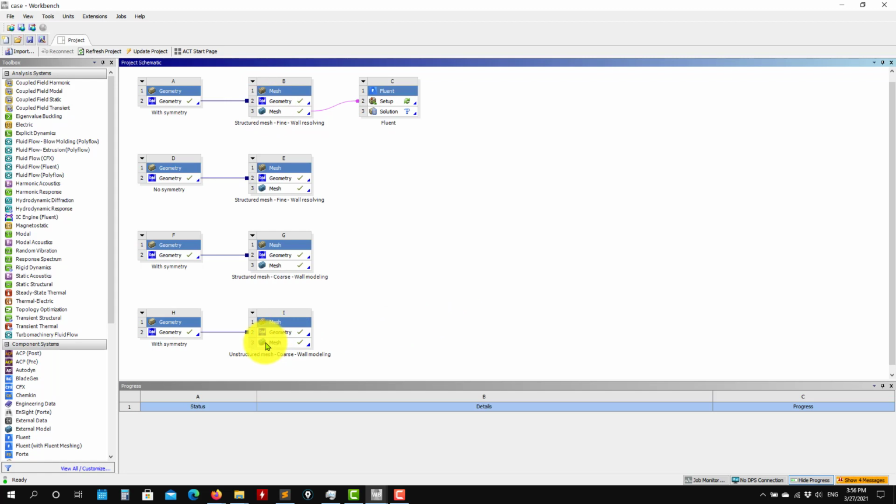And I think honestly, today's solvers, they can handle with no problem any kind of cells without losing accuracy, okay? So my advice is to stick with these unstructured meshes. But if you can afford the structured meshes, yeah, you can use those meshes. So see that after you generate the meshes, you connect to Fluent, you export it to Fluent, and you are ready to go.